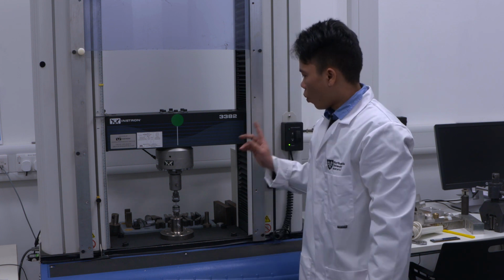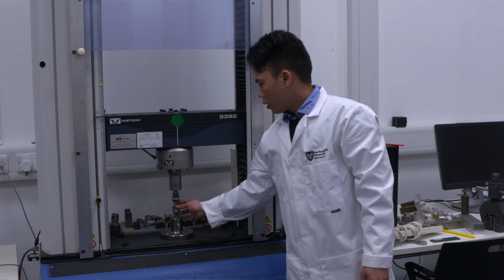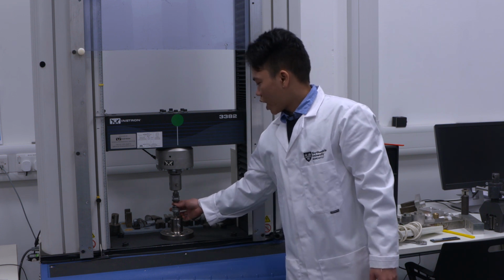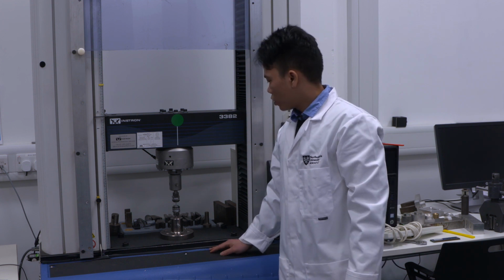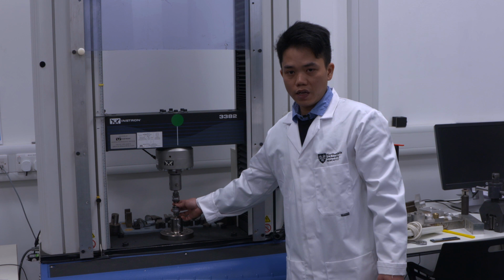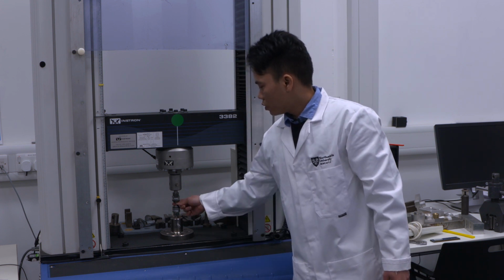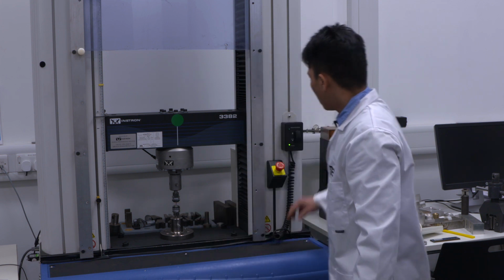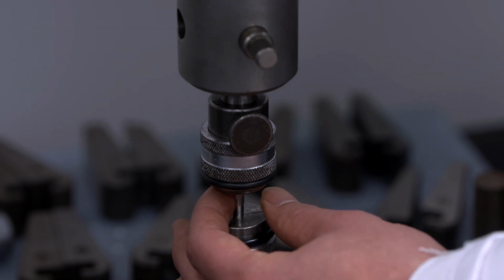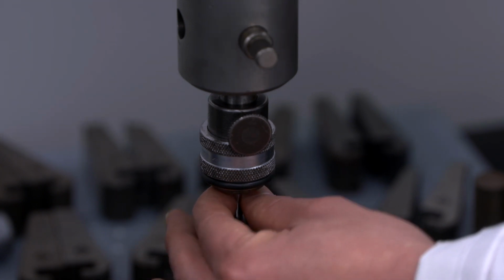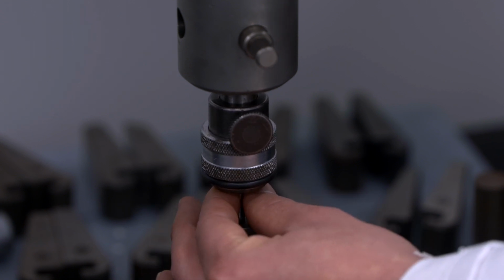One important thing you need to be careful about before the test: you have to always check the tension of the specimen. We need it to be zero at the very beginning. As you can see here, the specimen is still a little bit slack. So use your panel to move the crosshead up a little bit, very, very slowly, until you find a little bit of tension on the specimen.